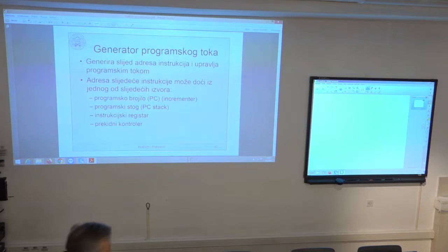So if the interrupt occurs, then this current program counter is written on some hardware stack, which I will describe later on. And after servicing this interrupt service request routine, the final instruction, return from interrupt, will again pop the value from this program stack and write this value over the program counter, just to go back to the main program where this execution was interrupted by interrupt request.